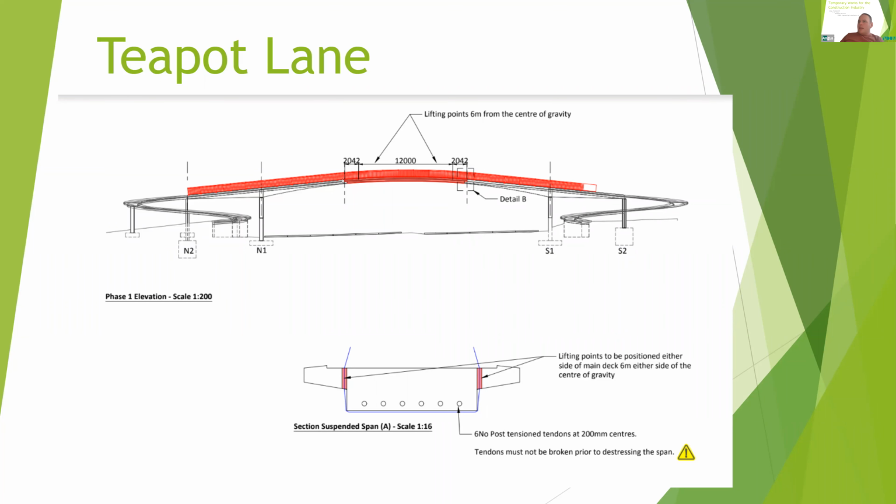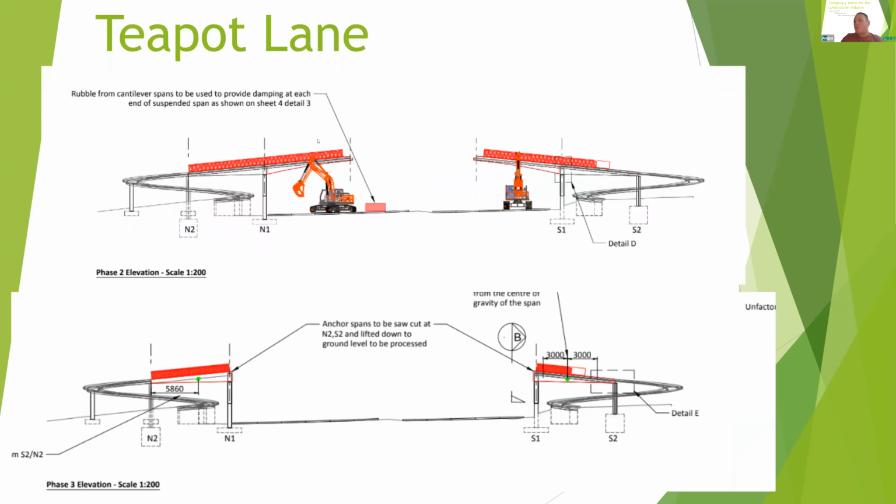This cantilever piece here, this was just normally reinforced, but it had a post-tension restraint at the end, and then the drop span was pre-tensioned, post-tensioned. So we lifted it out, maintaining the current load path, so keeping the supports very close to the ends of the slabs, as close as we could realistically. Drop them on the deck, place some rubble over either end of the, I think that's the next one, yeah,